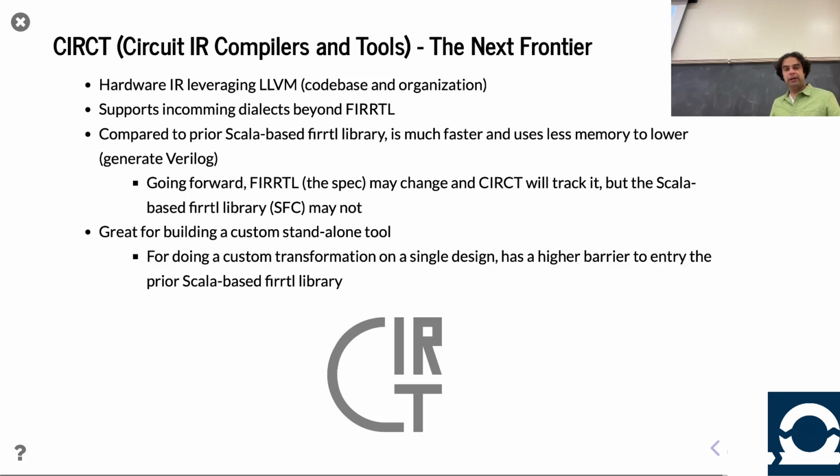The way it's being structured is CIRCT is actually a very general, very flexible, very inclusive IR. It has a lot of different things. They have something called dialects, and so there are multiple dialects. One of those dialects is FIRRTL. There are other semantics if you want to describe certain things, and other ways of describing hardware that are also supported. So that's the IR. There's also a tool that implements this, which is, for example, firtool I was talking about. This was largely developed by SiFive because, compared to the original Scala FIRRTL library, it's a lot faster and uses a lot less memory. And so that's the direction things have gone.